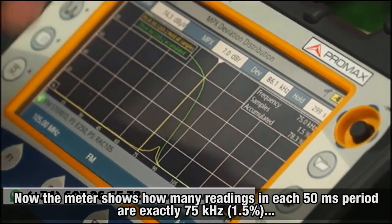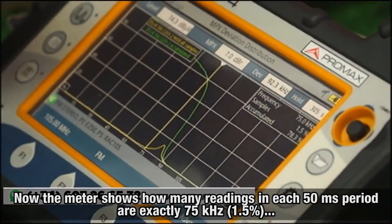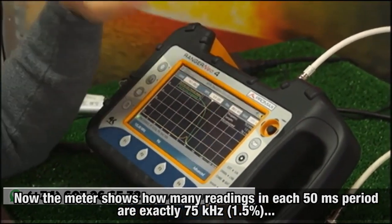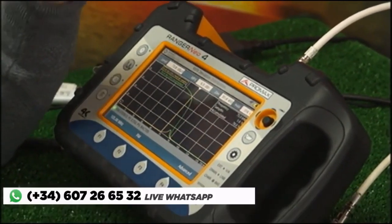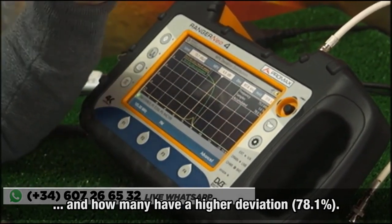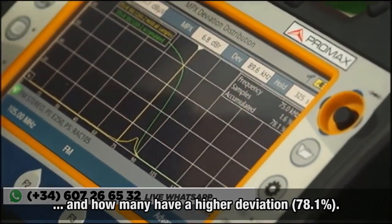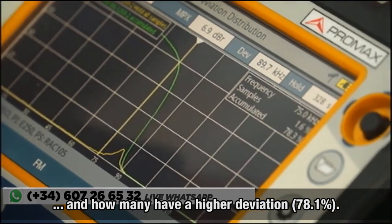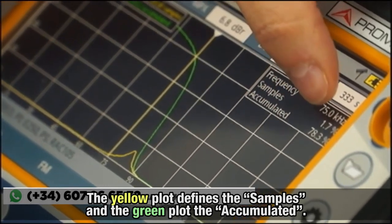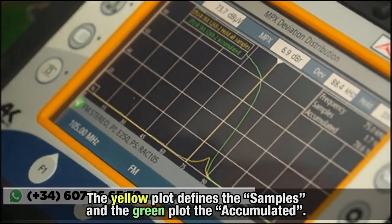And for that specific value, what the meter is showing me is how many of all these measurements that I took, keeping the maximum of each 50 milliseconds period, have an MPX FM deviation of exactly 75 kilohertz? That's 1.5%. And how many of them have an MPX FM deviation of 75 or higher? 78.1% of those readings have an MPX FM deviation higher or equal to 75 kilohertz. The samples value, the 1.7, comes from the yellow plot, and the accumulated comes from the green plot.